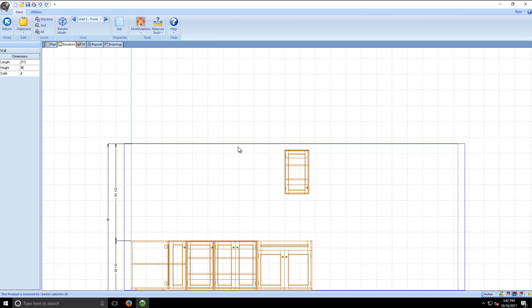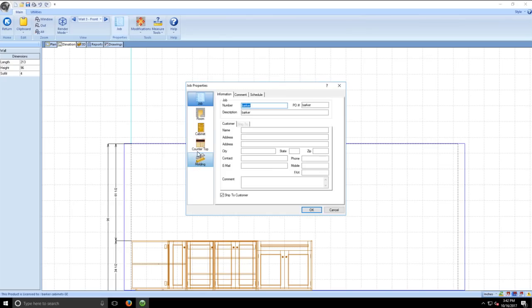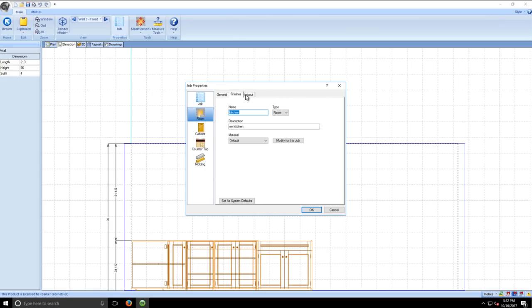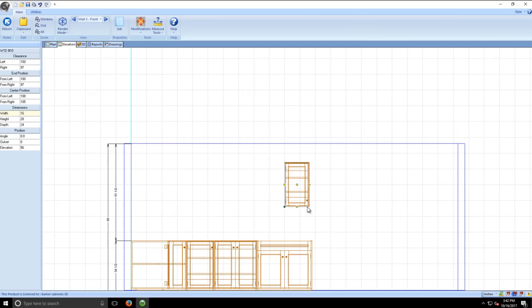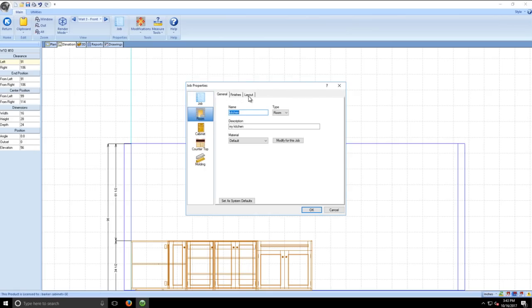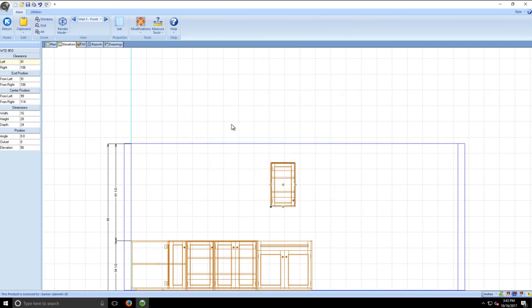Now, if you change that soffit, for example, you go over here to room layout, and let's just change that soffit to, say, 12, like it was before, like the 1980s cabinets, right? Put it to 12, and then we gotta wait. Oh, see, it knocked it down automatically. That's the nice thing about it. So you don't have to worry about these cabinets floating all over the place. Watch, I'm gonna go put it up here. Boom, it doesn't matter. It says, no, I know there's a soffit here. It's 12 inches up off the ceiling, okay? I want that to be 4, and I know that for a reason, because I want my crown molding to be 4 inches tall, and I want it to go to the ceiling.